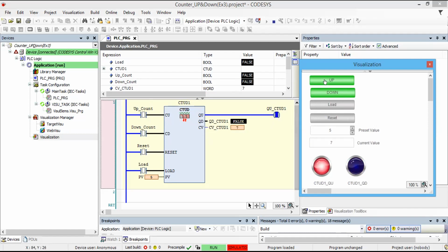You can still up count, but only the up counter output is high, right? So you can see that this variable is now showing in this virtual simulation environment. This is your HMI, so you can visualize. This is running on your PLC, but this is for humans. You can see that value in here, right?